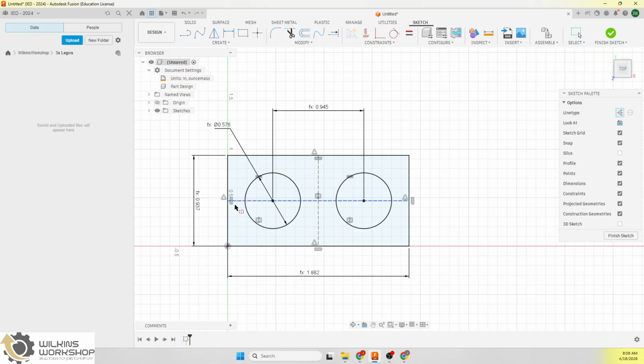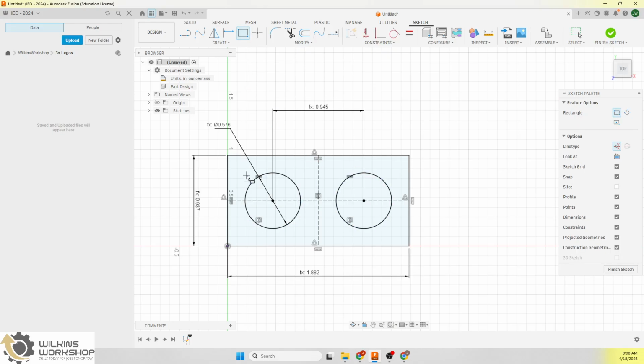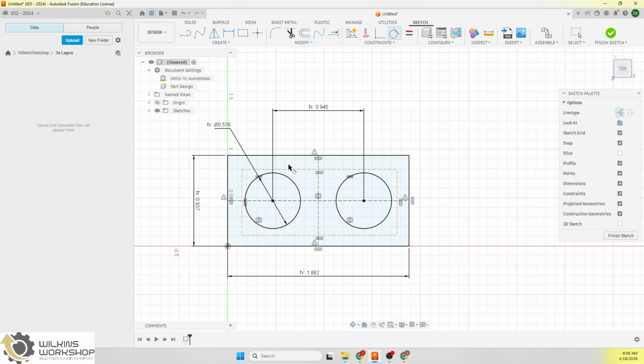And then for the underside, so this is the top side. These are what our dimensions should be when we measure the top side. Now for the underside, we're going to show what those dimensions should be. So most of these, we're going to make lines that are tangent to these studs because this is where the grip happens. So we're going to use the tangent constraint to make these lines tangent to these circles. And then we're going to do an offset of that line.